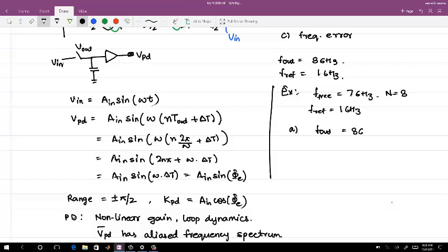Then you disable the divider path. And then you sample the output at the reference, sample F out with reference. So all the things which are happening in the divider are gone, and your energy is reduced. We will go into this kind of PLLs in detail.